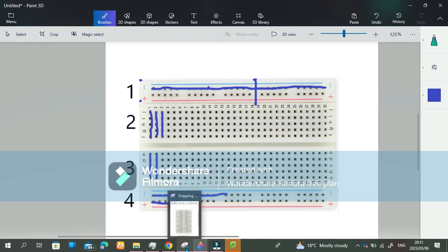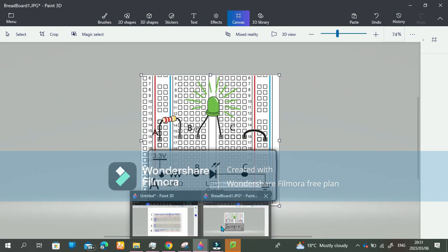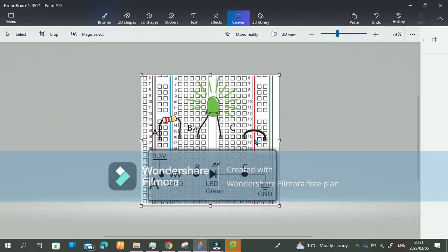Now, I'm sure you guys are wondering how you typically go about connecting a standard circuit diagram to your breadboard. As you can see from this figure that is now on my screen, I have labeled the terminals, or rather the nodes, of this circuit diagram as A, B, C. These are where our components are joining with either a voltage source or another component. How you position these components on a breadboard is shown in the figure above, where we have a resistor, an LED, and typically our ground and our power supply.